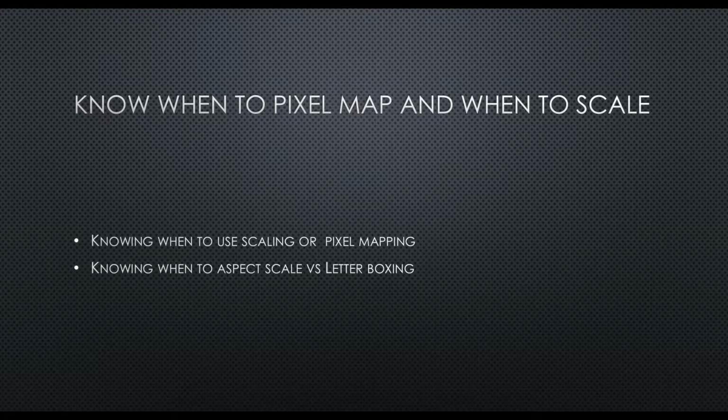Knowing when to use aspect scale versus letterboxing, and when to use free scaling. In my opinion, free scale should almost never be used. However, it's there, and on almost all the Novastar VX6S, VX4S, Node Pro Ultra HD, and all those other processors with the scaler built into it, you have a function called auto scale. Now, auto scale is a great feature. However, it's a free scaling feature.